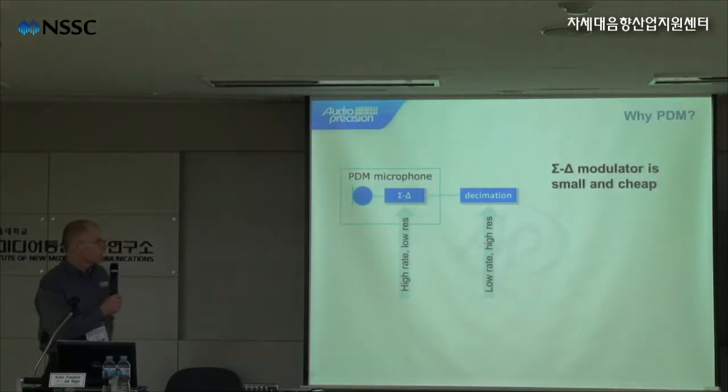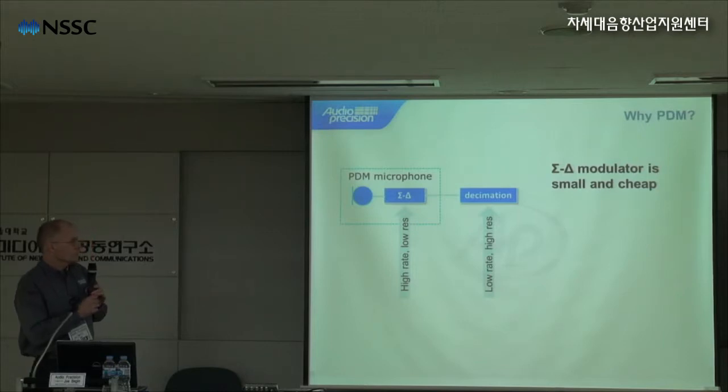Okay, so this slide asks the question, why do we want to use PDM, or these pulse density modulation microphones? So the PDM microphone has the microphone cartridge, and inside the microphone there is a high rate, low resolution sigma delta A to D converter. And there's a decimation,